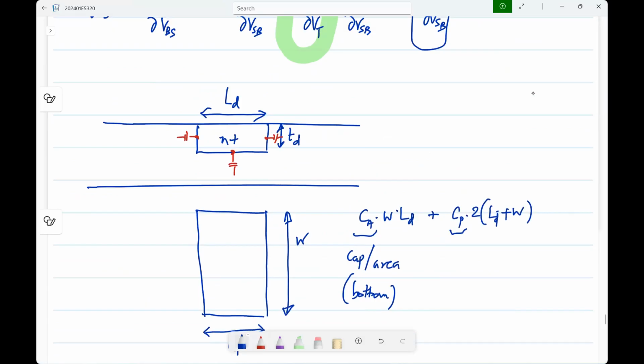Okay, so this is now capacitance per unit length. It will have the depth inside it. Okay, that will include the depth inside, but we don't have to worry about it. Like I said, all the parameters will be given to us so that we only look at the dimensions that we design, which is L, W, LD, all of these things, and calculate from there. Okay, so this is the sidewall capacitance, and this is nothing but the perimeter, right?